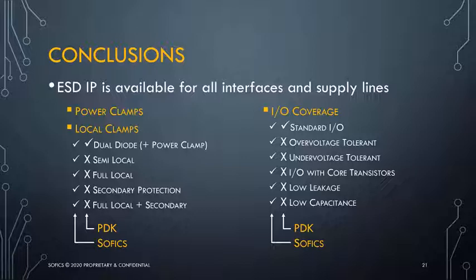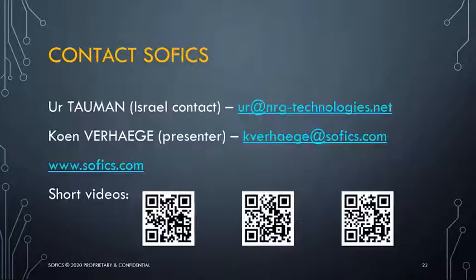In terms of I/O coverage, obviously also the PDK offers and covers the standard I/O ESD solutions. With the Sofics portfolio, we add to that over and under voltage tolerance solutions, enable IOs with core transistors, and also provide the very low leakage and very low capacitance solutions.